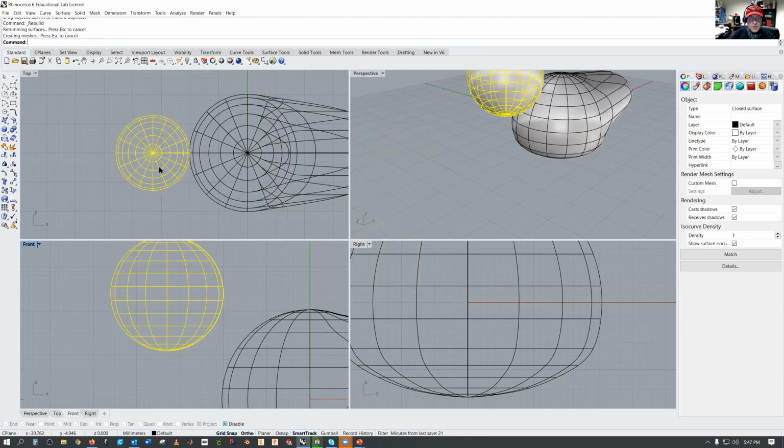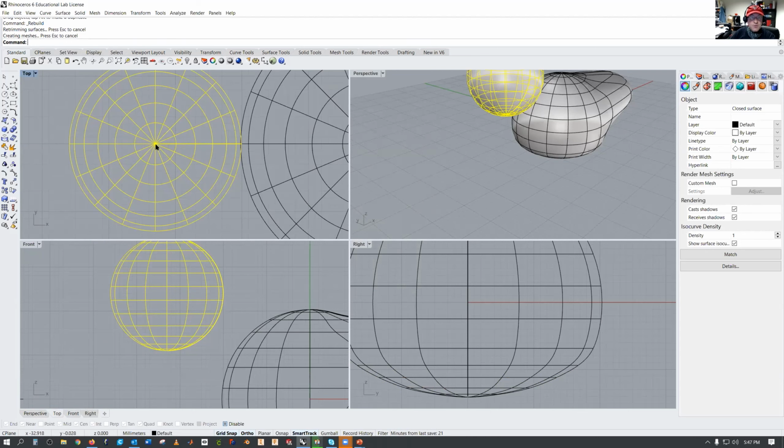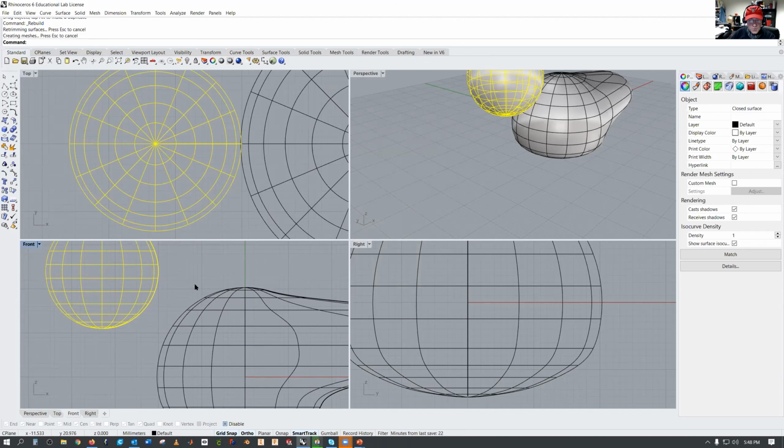So now we can do something similar with this guy. Oh, I made a mistake. So what I did was when I built the sphere, I put the seam this way from the left to the right. And it needs to be on the other side because what we're planning to do is cut into the body here and then cut into the head and then connect it with a neck, which is pretty cool. So they wind up being surfaces that become open because we're chopping a part out of them, and then we'll blend those surfaces together. And it'll do all the math for us, basically.